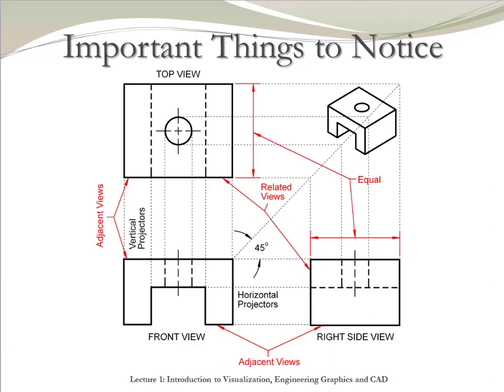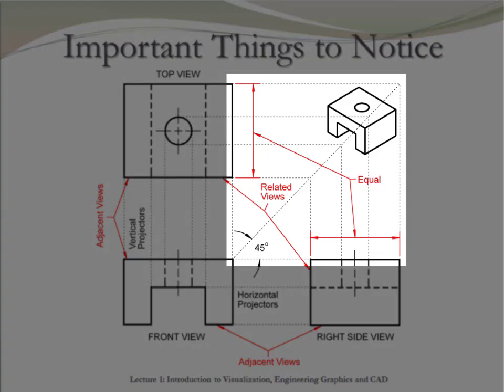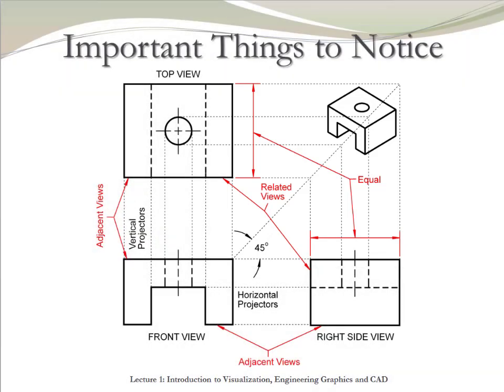The following are very important things to keep in mind when creating an orthographic projection. The distance from the front view to the top view must be exactly the same as from the front view to the right view. The vertical size of the top view must be exactly the same as the horizontal size of the right view. The 3 views must be arranged in an L format. Once you are done adding all the details to the views, you're done with the orthographic projection.